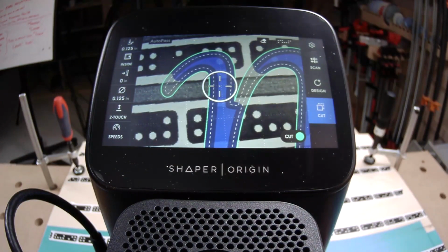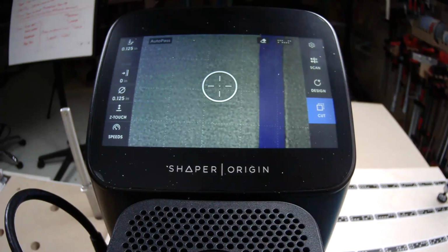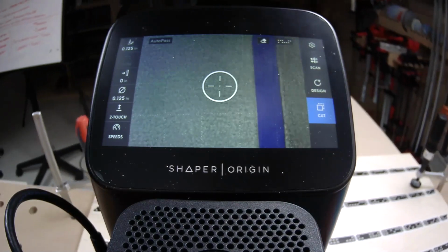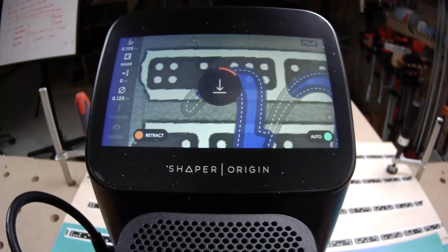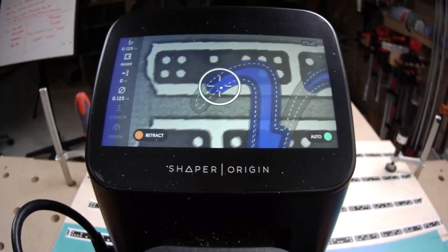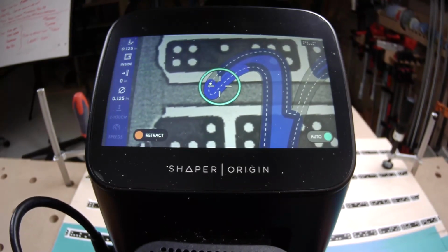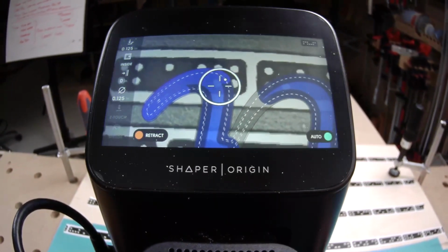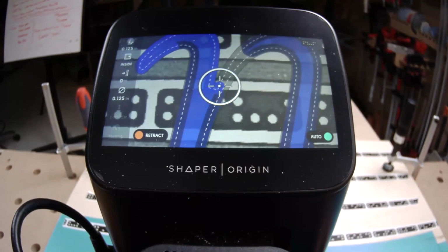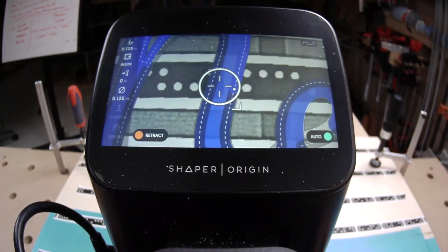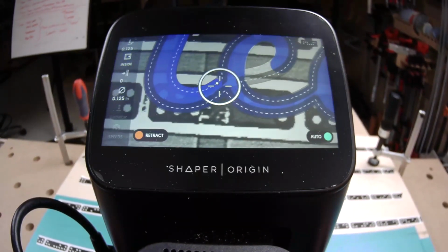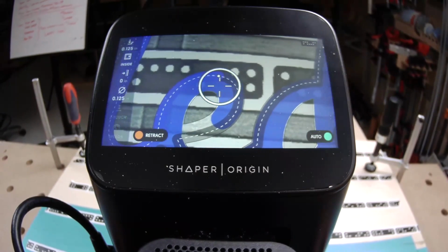Yeah, that's the trade-off there. So the down cutting bit really does a great job of keeping that vinyl mask pressed down against the crisp edge that you want for that sign, but it's also pressing all of that sawdust or all of that plastic waste, if you're working with HDPE, all of those chips down into the cut, which causes a lot of friction when all those chips build up and the router bit's trying to make room for itself. So you have to be cautious with plastics that you don't melt things. You have to be cautious for wood that you don't start a fire.